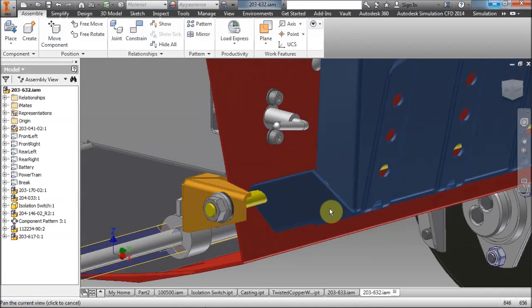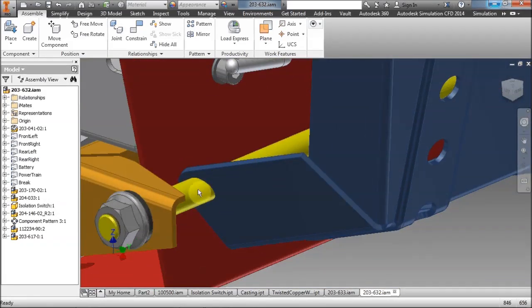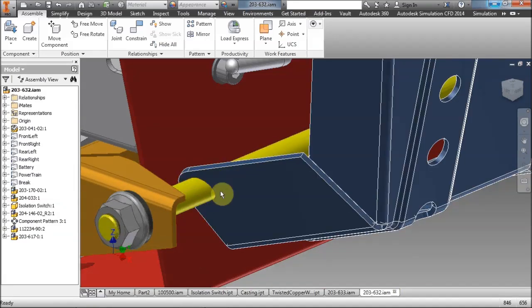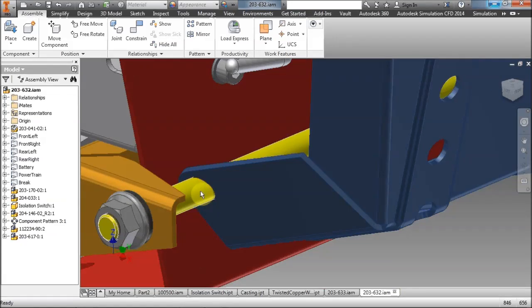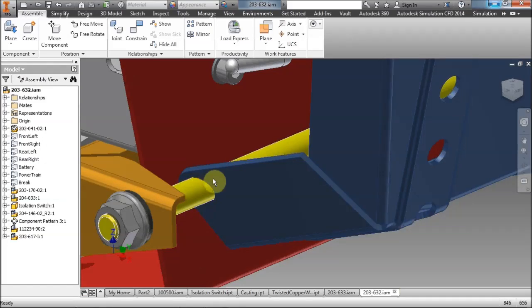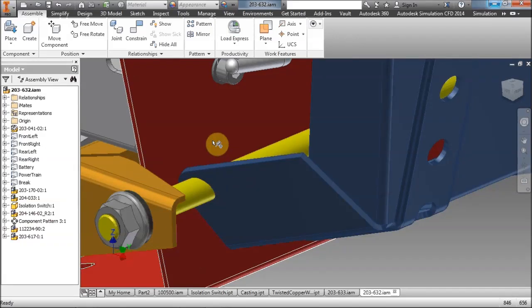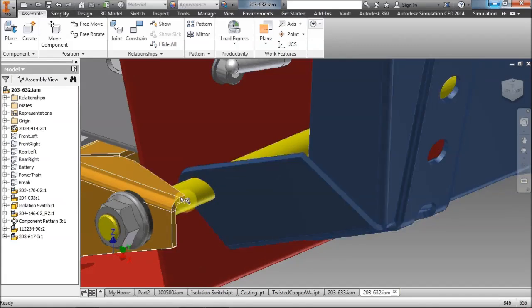Now here's a fantastic tool in sheet metal. We've got the bar going through, interfering at the moment with this sheet metal component, so I need to cut out the sheet metal component with this bar. Now the problem we've got is the sheet metal face or flange is at an angle. So if we cut this out at the moment, in 2014 this would have cut it out and given us a circle, well, an ellipse at both sides, but offset from each other, and not really giving us the correct cutout. So when we create the flat pattern, we're not getting the correct cutout that we require to allow us to put this shaft through the hole.